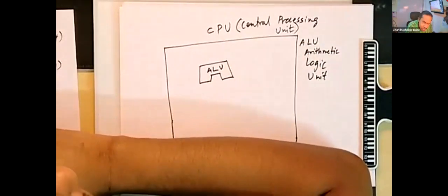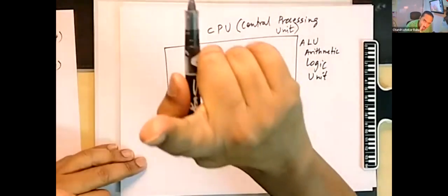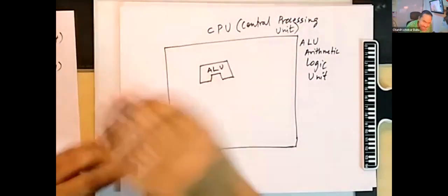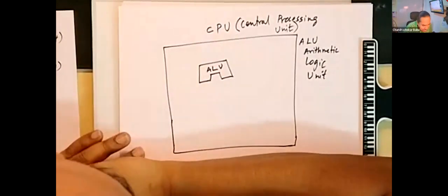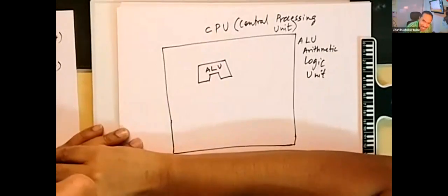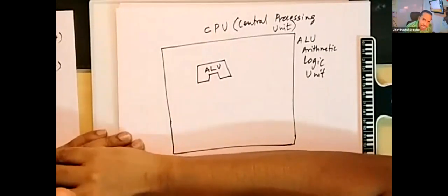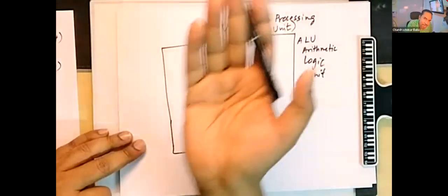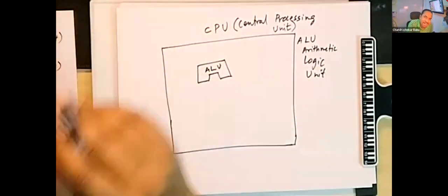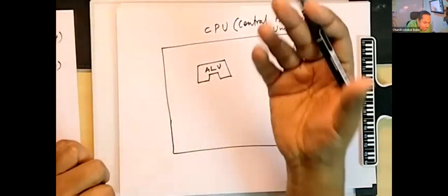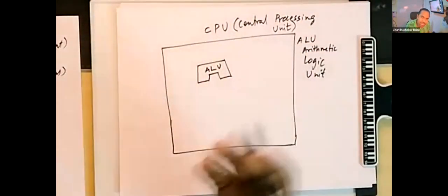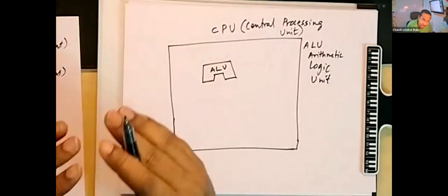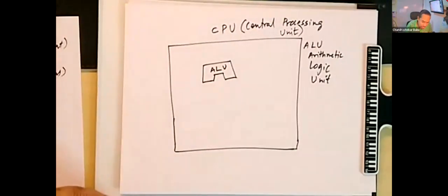When I say all arithmetic operations, what all arithmetic operations can it do? In reality, only one operation, addition. That is it. It is a big, shocking revelation. An ALU contains mainly an adder. It just adds numbers. If you know how to add numbers, you can also subtract numbers if you represent a number in signed format. If you represent -3, -8, all these numbers, you can just add the negative number and the positive number, and you get subtraction, right? That's how this ALU is designed to be.